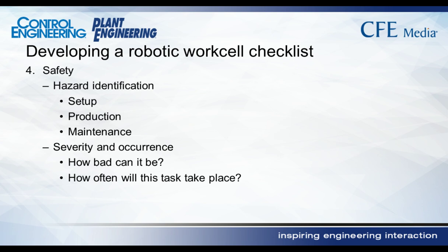Maintenance. So if you're doing maintenance in the cell, around the cell, or if there's hazardous gases that are being introduced in the cell, how do you lock out and tag out those things so that all hazardous energy is removed from the cell prior to doing maintenance?